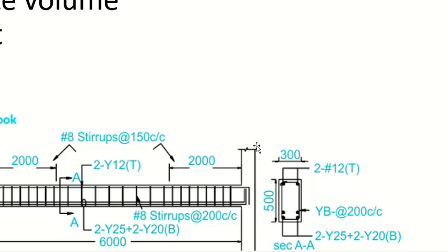Okay, the hooks. I told you normally 9 times dia or 10 times dia, 9 or 10, the other end. So I will add it, obviously, the hooks. So 9 times dia. What is the dia?